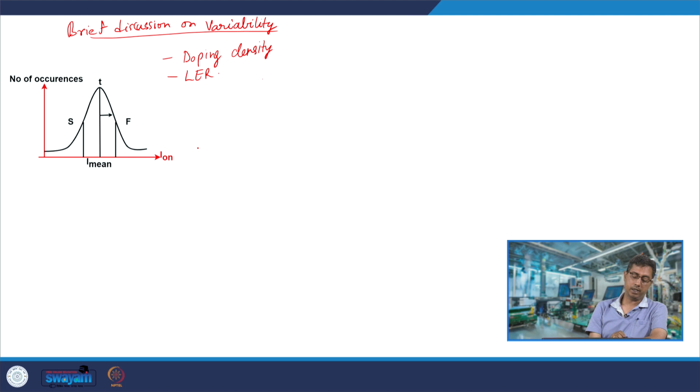Now, for a transistor, Ion is plotted over a large number of samples, and it follows, suppose, a Gaussian profile. In that case you find the, say, 3 sigma or 2 sigma values and call one the fast corner because it has a larger Ion, another the slow corner because it has a smaller Ion, and the mean the typical corner. This happens for the P MOSFET as well as the N MOSFET.